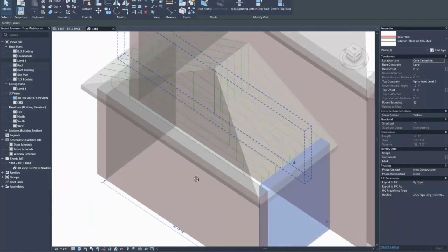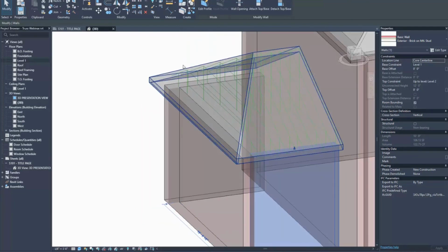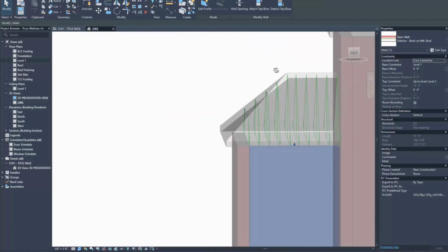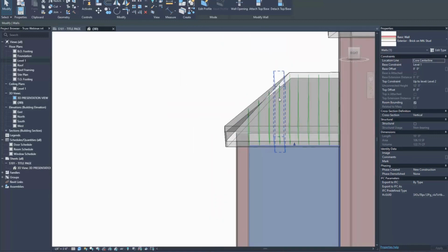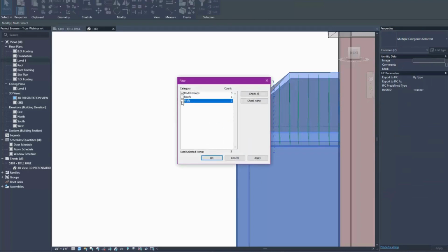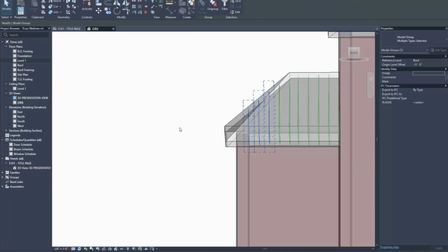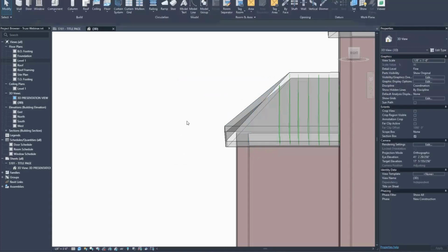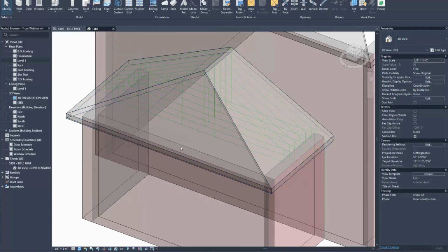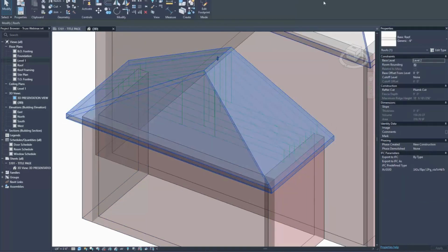You will now notice we have some girder trusses placed, and you'll see that the shorter ones are here too. What I'm actually going to do is go to this view here like so, and I'm only going to keep this one and this one. I'm going to get rid of the rest. And in the filter, you can just uncheck roof and walls, and those 3 envelopes are what we want to get rid of. They're model groups. Okay, so now what we are going to do is go ahead and frame the hip end.